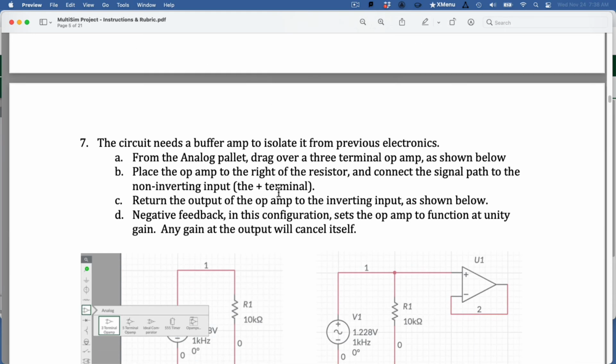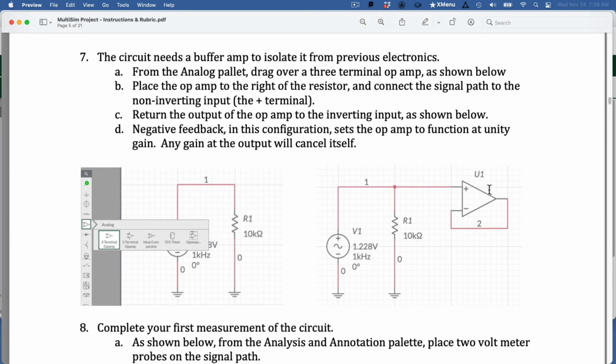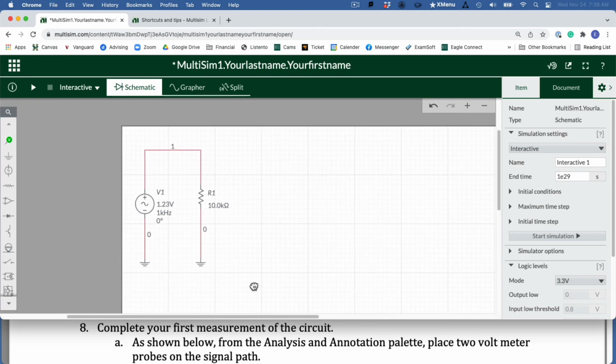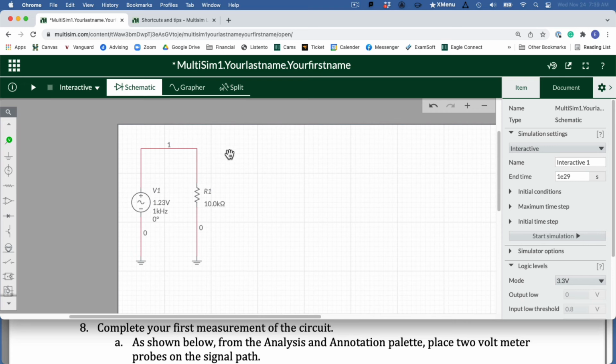And what else are we drawing here before I end the video and go on to the next one? We'll add one more thing. We're going to add a buffer amp. So the input, this 10 kilohm resistor here defines the impedance to ground as 10K. And that's about normal for a line level input. Usually they're a little bit higher, but that sets the input impedance, and we want to do that. We want to set the input impedance because the op amp that we're about to go into has a very, very high input impedance. So this will lower that down to 10 kilohms.